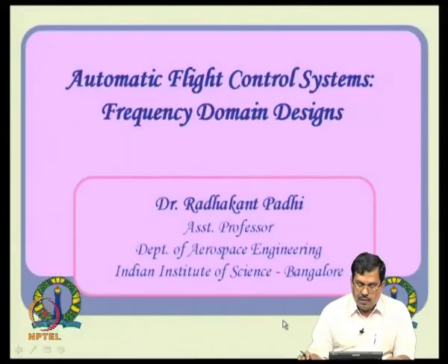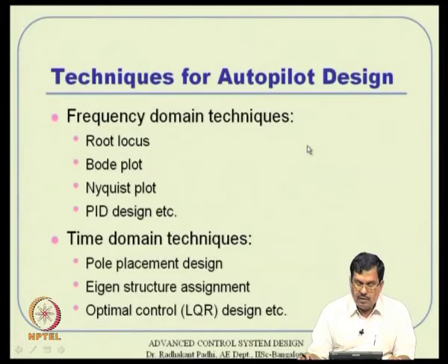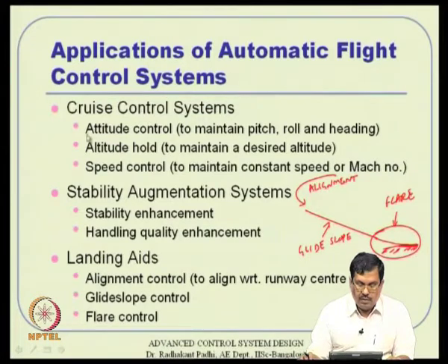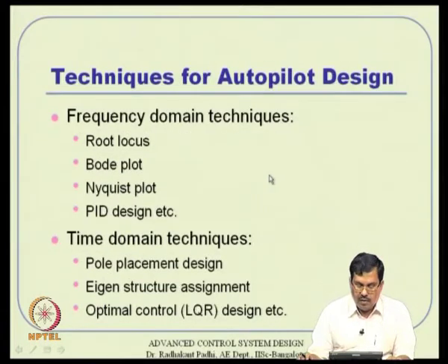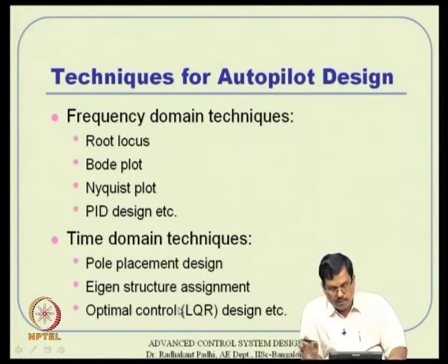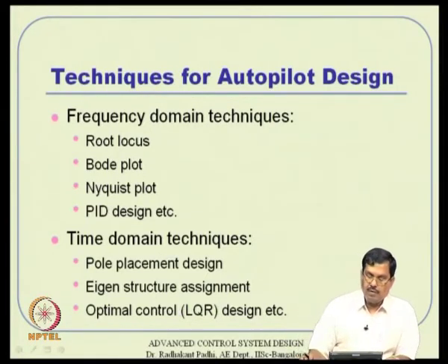Okay. So, let us see, this frequency domain design approach is what I am talking about here. And remember, the frequency domain means we will largely confine ourselves to this, and I will take the help of root locus and to some extent the PID design concept. Bode and Nyquist are analysis techniques, and I think they are also useful, but we are not going to discuss them here. And here we will discuss some attitude control and then speed control, things like that. Okay. And next class probably we will go through some of these time domain techniques, and then we will follow it up with the concept of gain scheduling and things like that.